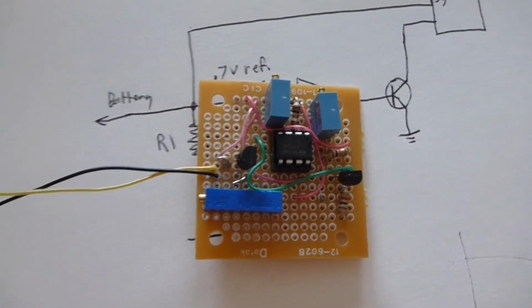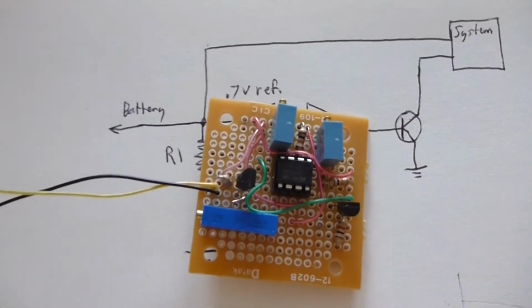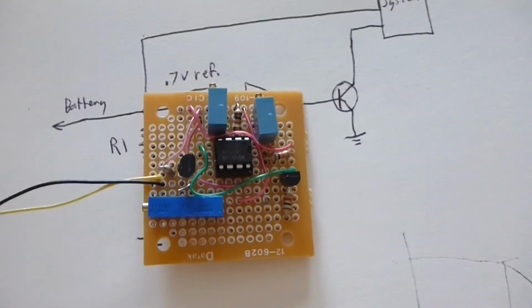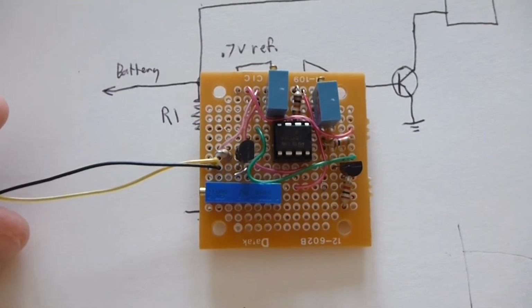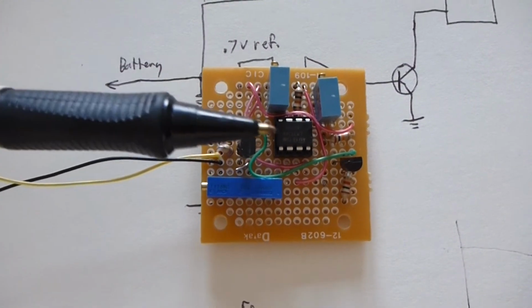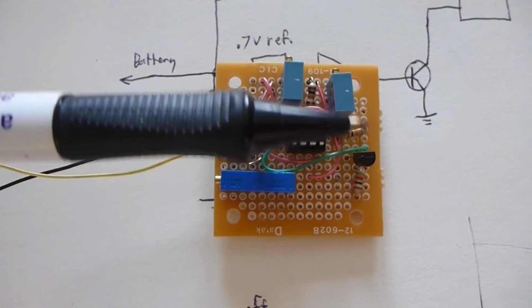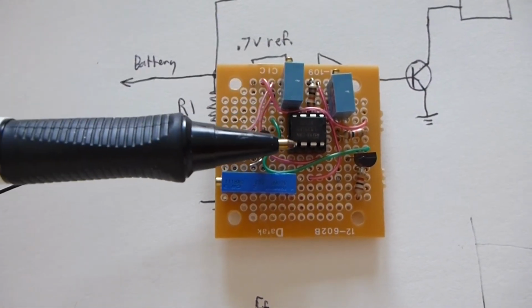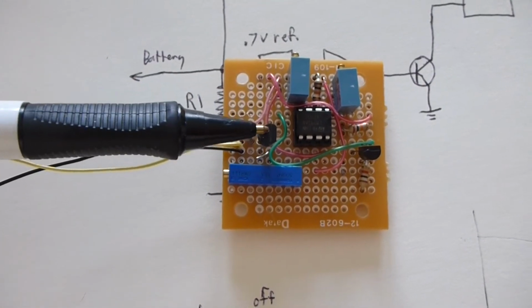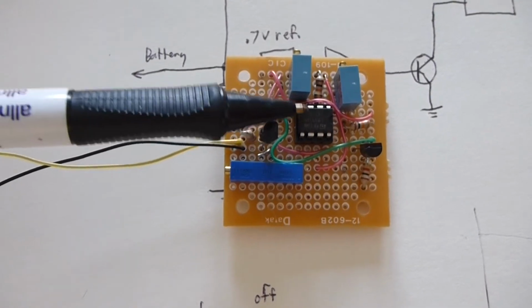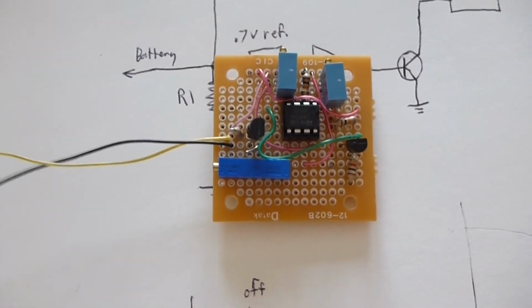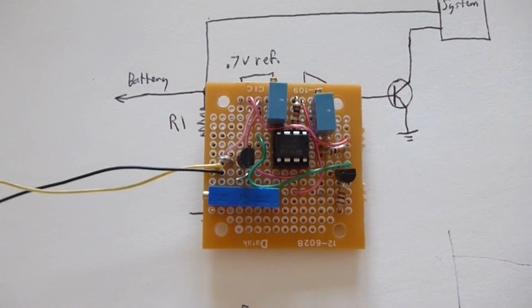Unfortunately, we put this circuit together. I built this and we will not use it. Two problems. One, it's actually kind of hard to get this transistor to fully switch states because of the low voltages we're dealing with here. Two, this voltage regulator and the comparator actually draw a decent amount of current even when the system's off.